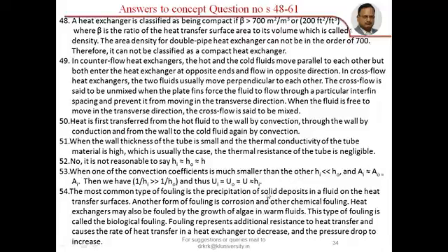So in such a case, even though the data is not given for determining the condensing heat transfer coefficient outside, as an approximation, you can take the overall heat transfer coefficient as the inside flowing fluid heat transfer coefficient and proceed. That is the advantage of assuming Ui equal to U naught equal to U approximately equal to HI.